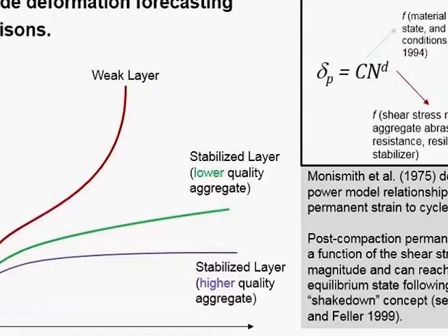Yesterday, I tested 4 sections out at Min Road, and we generated permanent deformation on the asphalt layer between about 0.04 inches and 0.11 inches. So the one that was 0.11 inches left a small indent in the asphalt surface, but it was because of the underlying foundation. We're in this intermediate situation there.